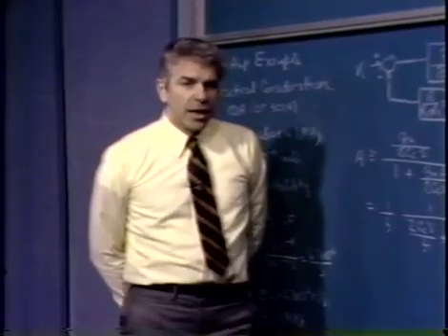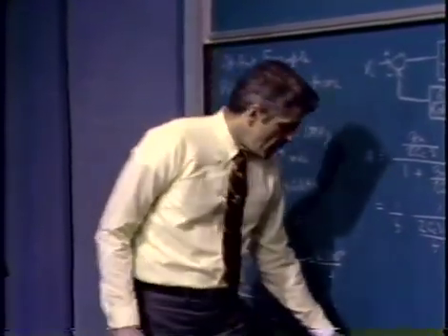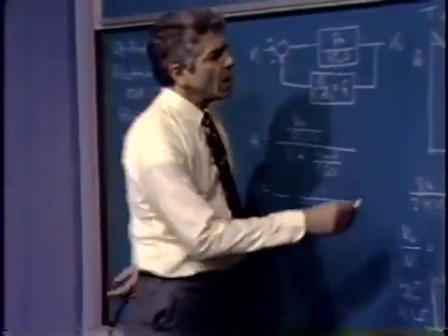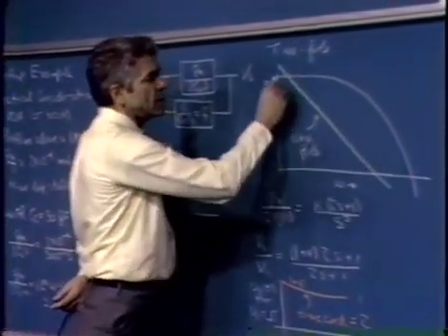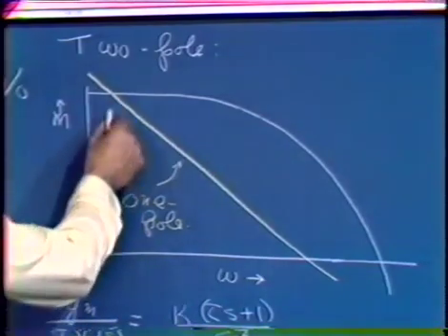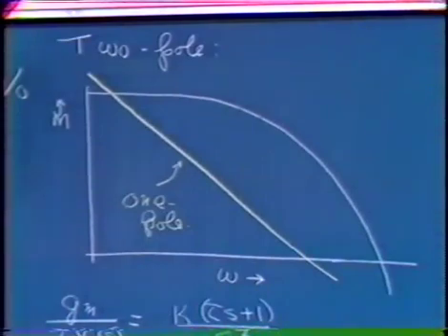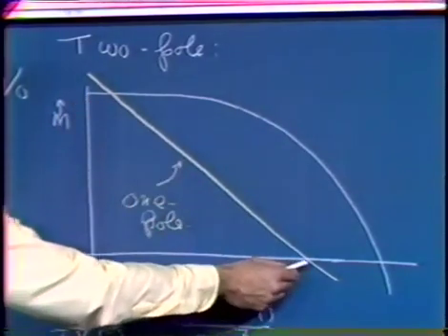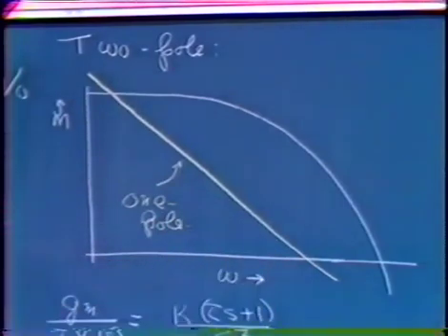Another possibility is to consider the following. Let's suppose that this is the open loop transfer function of the amplifier without compensation when we consider the effects of loading by the compensating network. In general, the loading of the compensating network usually doesn't change that curve much. So let's suppose somehow we know that this is the uncompensated open loop transfer function for the amplifier. If we use single pole compensation and possibly adjust it for unity gain at a megahertz or something like that, this is the approximating function.